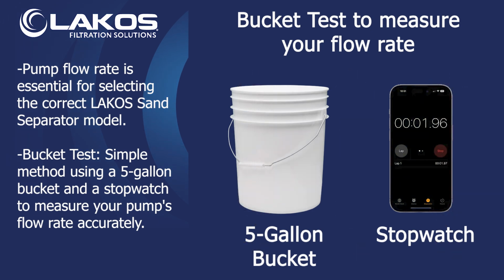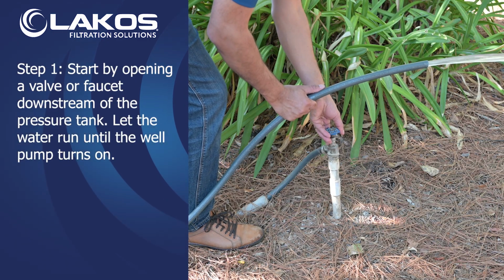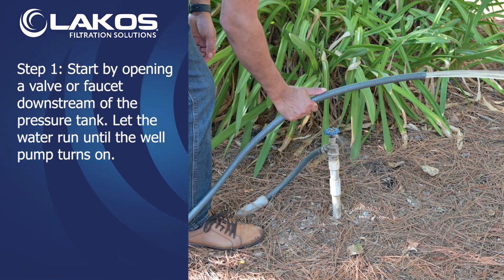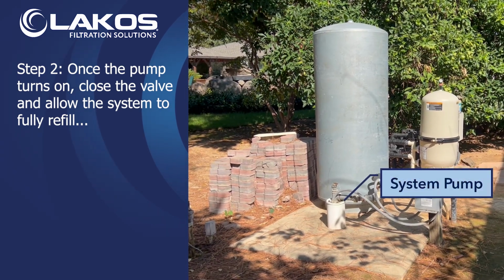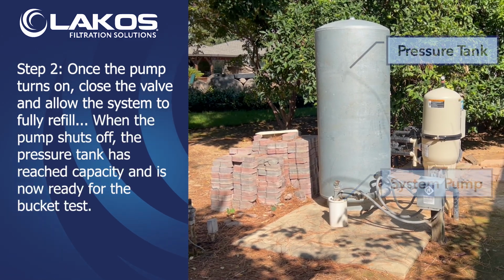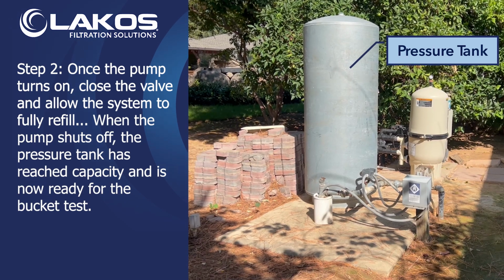So before you choose a LAKOS solution, let's walk through a simple way to determine your true operating flow rate, using nothing more than a 5-gallon bucket and a stopwatch. Start by opening a valve or faucet downstream of the pressure tank. Let the water run until the well pump turns on. Once the pump turns on, close the valve and allow the system to fully refill. When the pump shuts off, the pressure tank has reached capacity and is now ready for the bucket test.